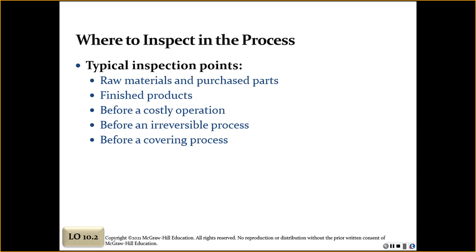and the hardware. We want to make sure that if the hardware or the software fails on one server, because we have 3 servers for the energy management system, it's going to fail over to the next one if the software or hardware fails on the primary server. So we're checking functionality for that. We're checking that if we push a button to open a breaker, that breaker opens. If we push a button to close the breaker, we want to make sure it closes and it stays closed. So we're always inspecting it.